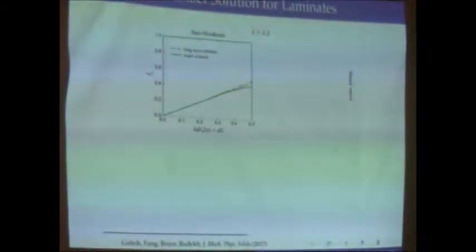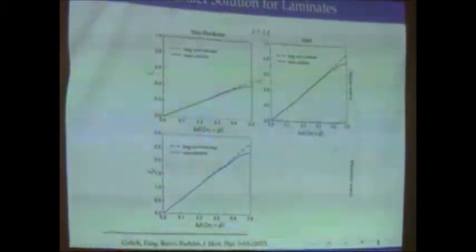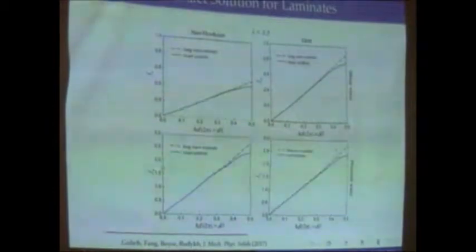So you have the long wave estimate, but it works surprisingly well for a very wide range of wave numbers. And here the exact solution is for shear waves, also for Gent material. The material is already quite significantly deformed, and also for the pressure wave we have these estimates, and you can observe that the difference between these curves is not really very significant.